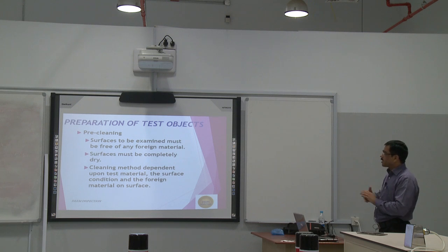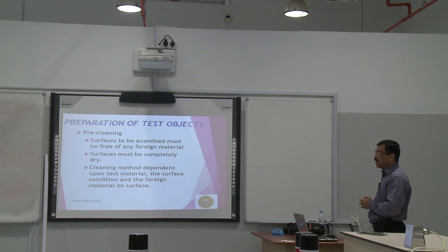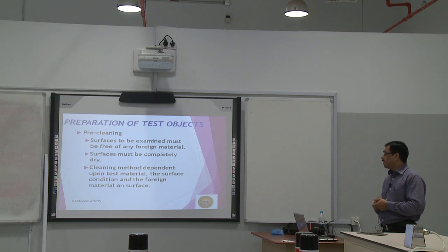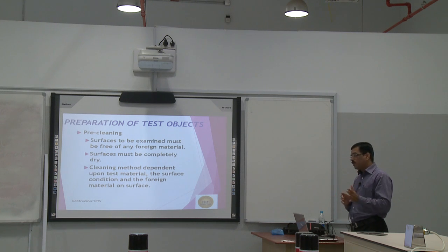We already explained regarding this one. Pre-cleaning: the surface to be examined must be free of any foreign material, and the surface must be completely dry. The cleaning method depends upon the test material, the surface condition and the foreign material on the surface. So depending on our situation or our job, we can select any cleaning method for the surface preparation.